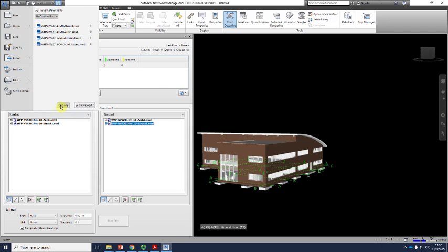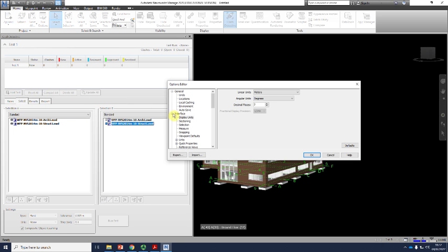To check the units, you go to Options, expand Interface, and go to Display Units. This is where you can change the units. It's advisable to leave it in meters, and if it's millimeters, it's 0.001 meter, not 1 meter. These are decimals, maybe 3 here. So this is how you change them.